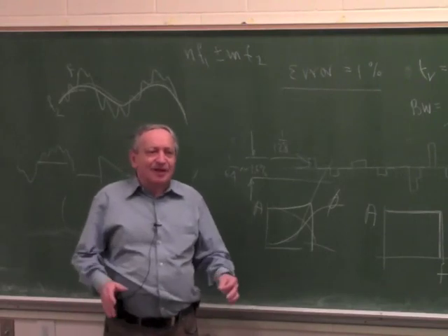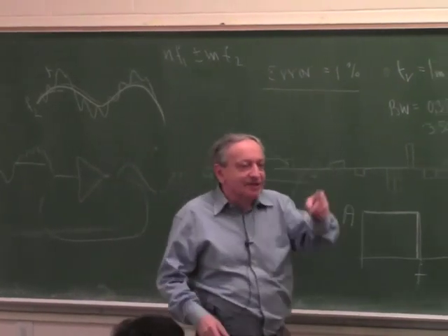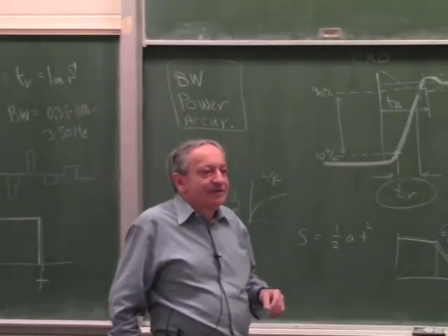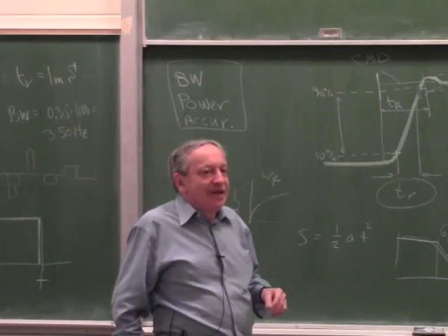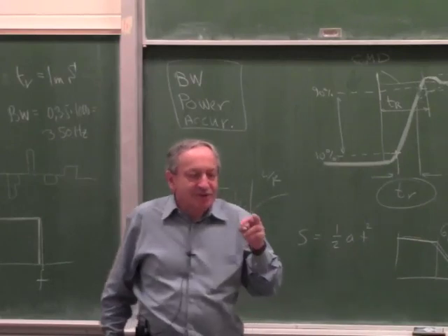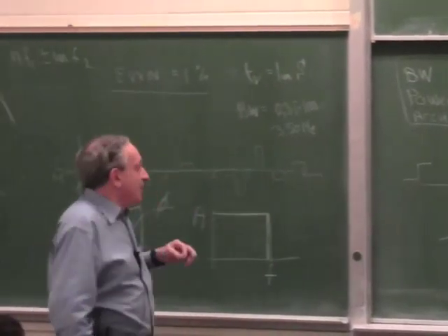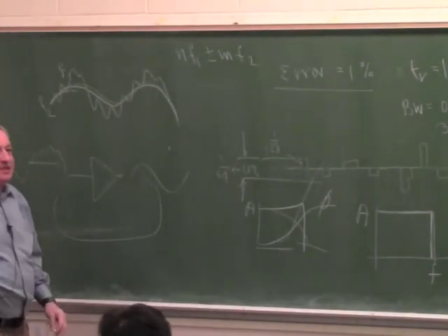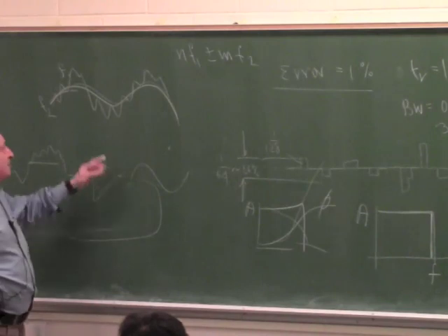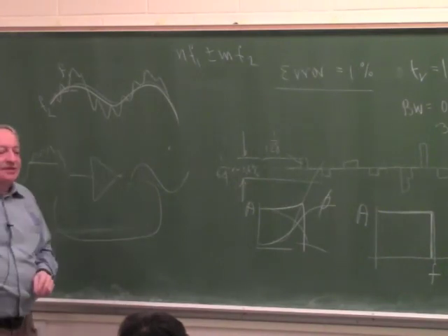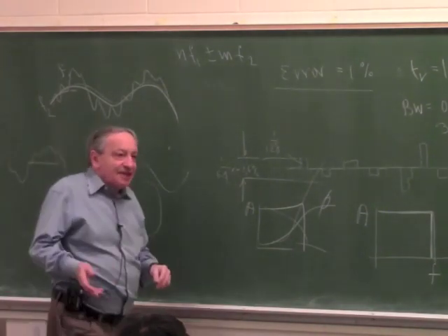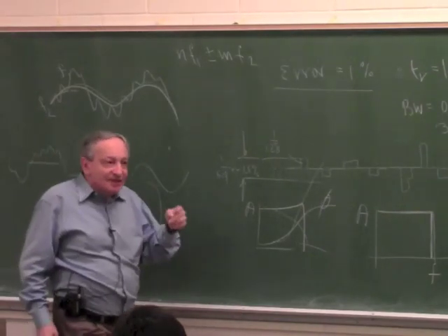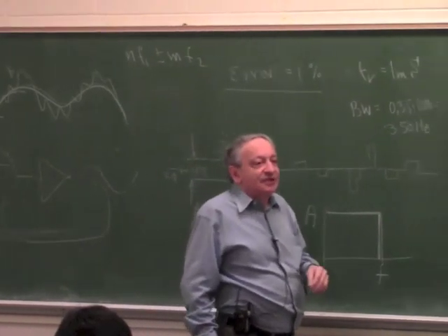A third reason is practical, it has nothing to do with theory. Yes? If you limit the bandwidth, can you get better gain at the regions you want? Yes, but I'm saying something different here. Even if the amplifier overall has limited bandwidth, I don't want to feed into it a high frequency. So one reason is aliasing if it's a digital front end, one is intermodulation, but there is another reason why I don't want to feed into it a high frequency.